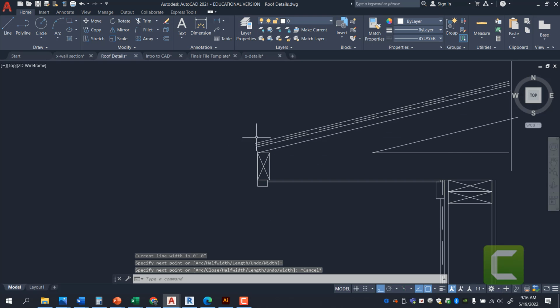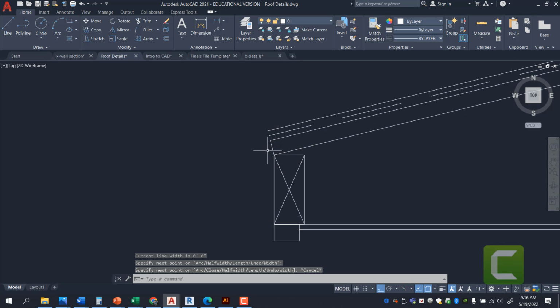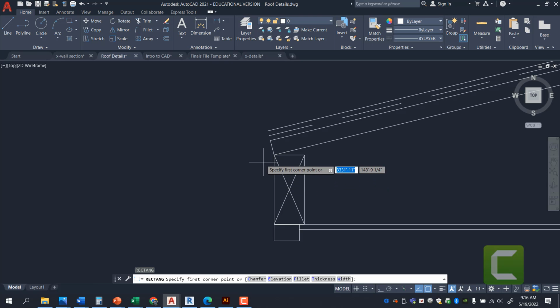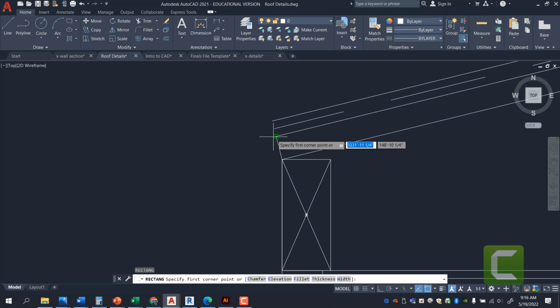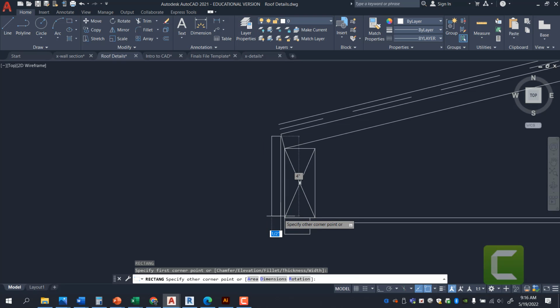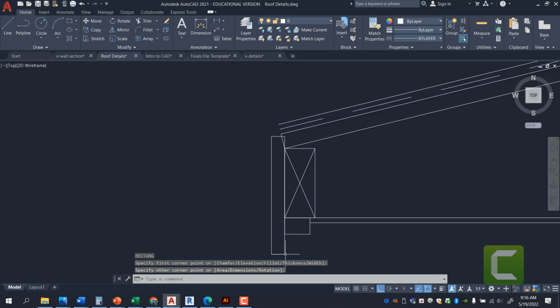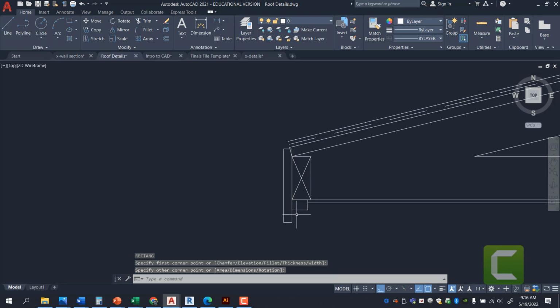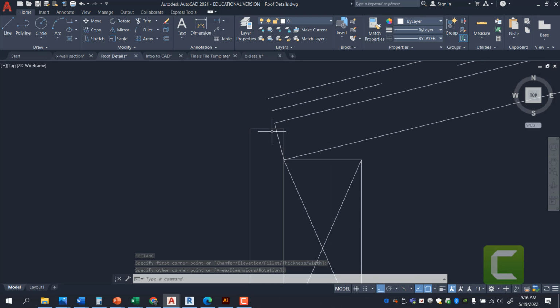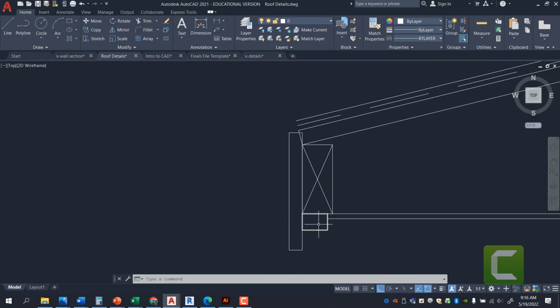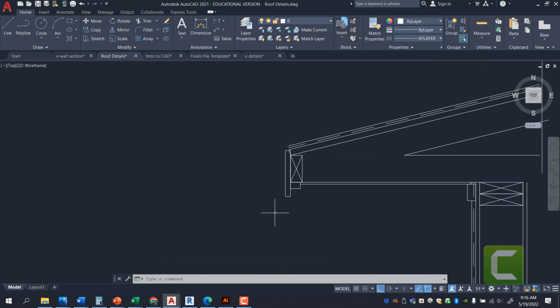Now, I like to finish off this edge with my fascia board. Right off the bat, fascia board gets placed right here. Your fascia board should exceed the length or exceed the trim on this side, because you really want to create this as a drip edge.